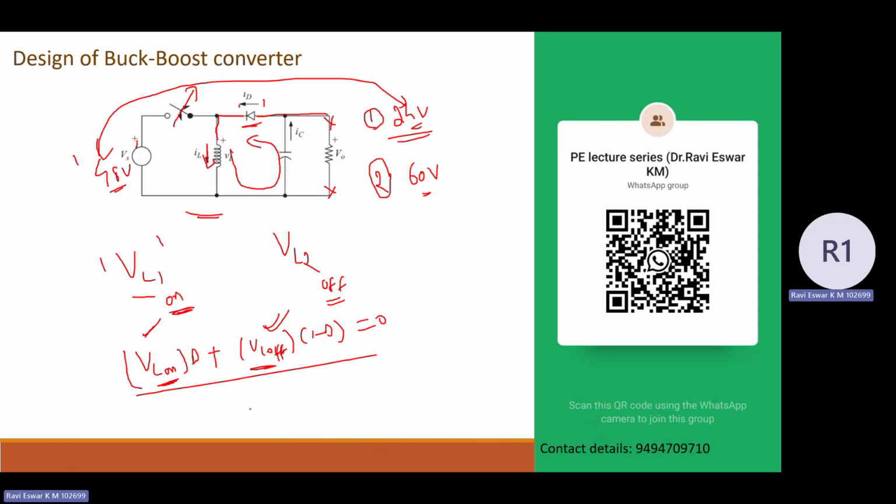So the same interfacing converter is going to perform the buck action. Again, I want to change my load. Now my load requirement is 60 volt. Without changing the converter interfacing system, the same converter is going to perform boost operation, and the voltage is going to be stepped up from 48 to 60 with the application of duty greater than 0.5.